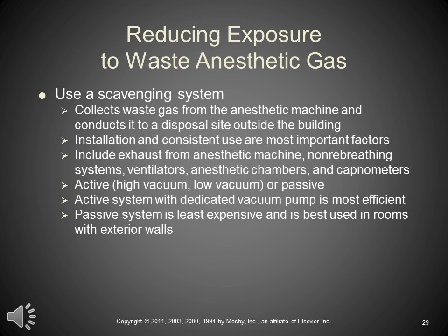Everything should go. There are active or passive systems, and the active system with a dedicated pump is the most efficient. It's going to suck the gas out of the room. A passive system is certainly the least expensive and is best used in rooms with exterior walls.